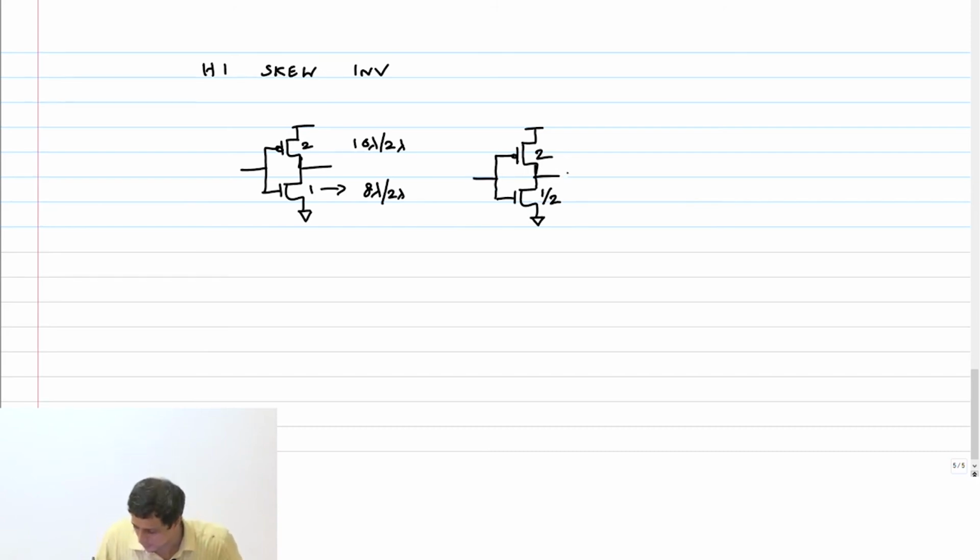Right? So now before we start calculating the logical effort of pull up and pull down, which one will be greater than 1? Which one will be less than 1? Pull down will be greater than 1. Pull up should be less than 1. Right? That's the aim. So what's the capacitance of this? 5 by 2 C. Okay.